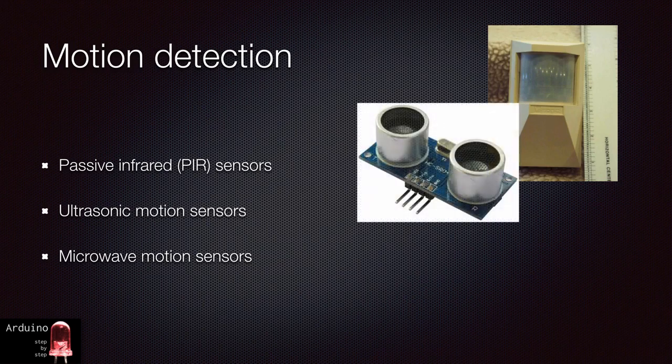An ultrasonic motion sensor uses ultrasounds to detect moving objects. Just like bats, an ultrasonic sensor emits ultrasounds at frequencies from 30 kHz to 50 kHz and then picks up their echo. These sensors often measure the time a signal takes to return, and from that it can calculate the distance to the object. Therefore, ultrasonic sensors can calculate both distance from an object as well as whether the object is moving. We will be looking at ultrasonic sensors in the following lecture.